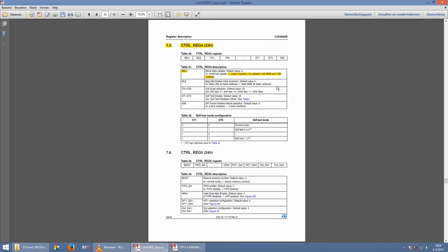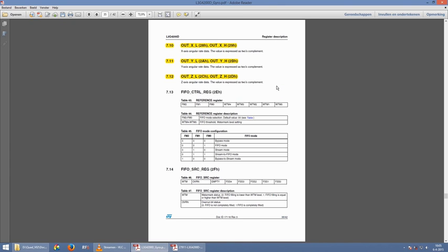And last but not least, we can read our angular rate data from the X, Y and Z output registers. The angular rate data is a 16-bit value and is divided over 2 registers of 8 bits. To get the complete value, the bits need to be shifted to their correct positions.